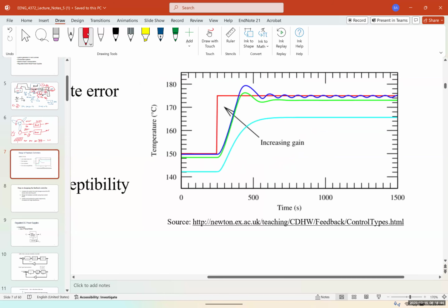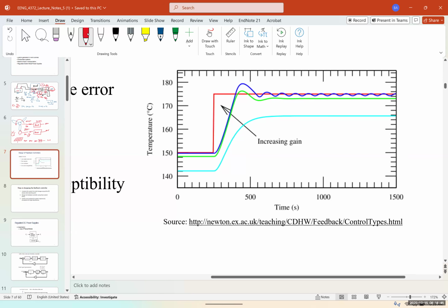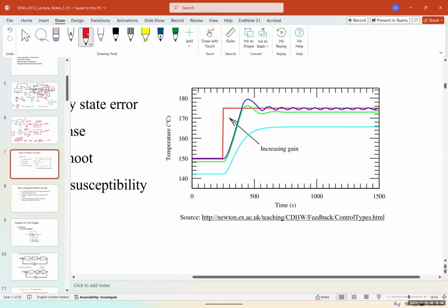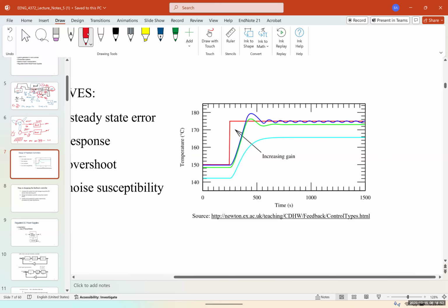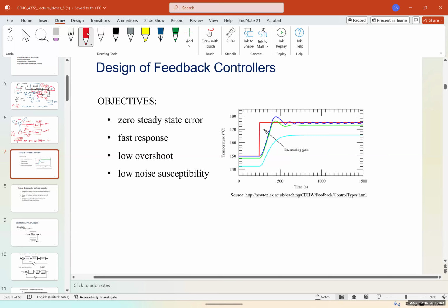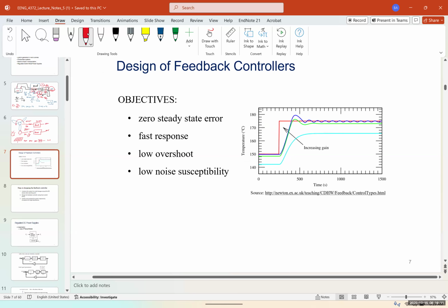And you can see here, by increasing gain, we're gonna probably have overshoot. As you remember, I don't know if you had that in control system, but we have overshooting, undershooting, and if the gain is too low, it's not gonna reach the final voltage. If it's too high, it's gonna overshoot and it's gonna resonate, which is not good. So we're gonna have the right amount of feedback control system for the feedback.